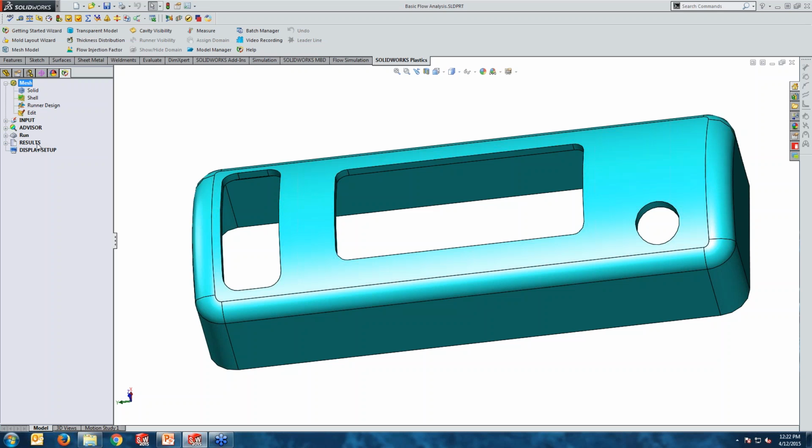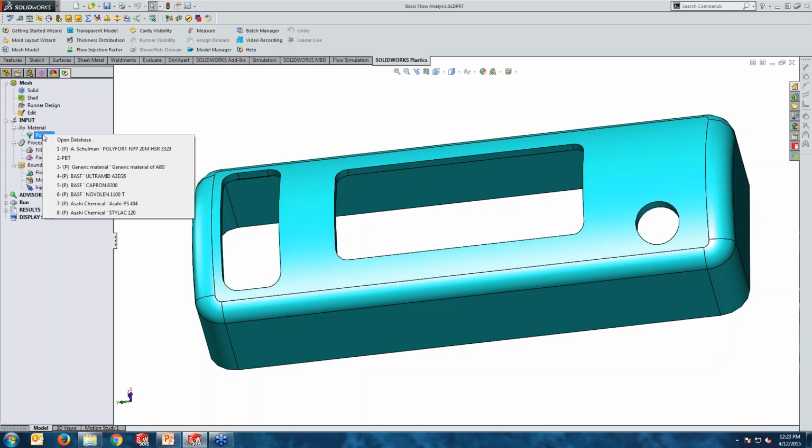So we have to say, what are my inputs or what do my boundary conditions look like? We can always get assistance from the software. We run the project and we look at the result. Let's expand the input section. In your input section, what you can see is the material definition. So right click and you have to say what sort of material I have used.